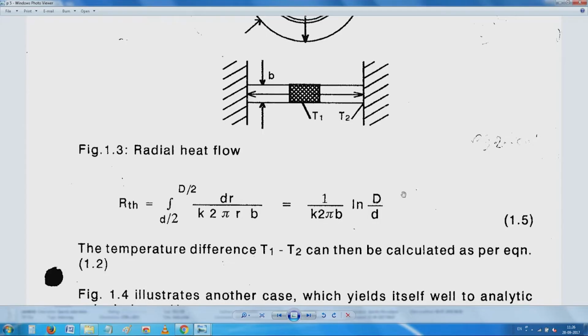This follows that Pentium cooler which I have shown you. If you see that radial modeling there, base of it is, if you see that earlier first picture I showed you, there is a circular heat sink, and then at the base of it the square pad is mounted, and then from there radially we have heat sinks. At those points when you are calculating the way the heat reaches the end point, you will be able to use these expressions easily, and this is already what is built into most of the CFD or FEA packages.